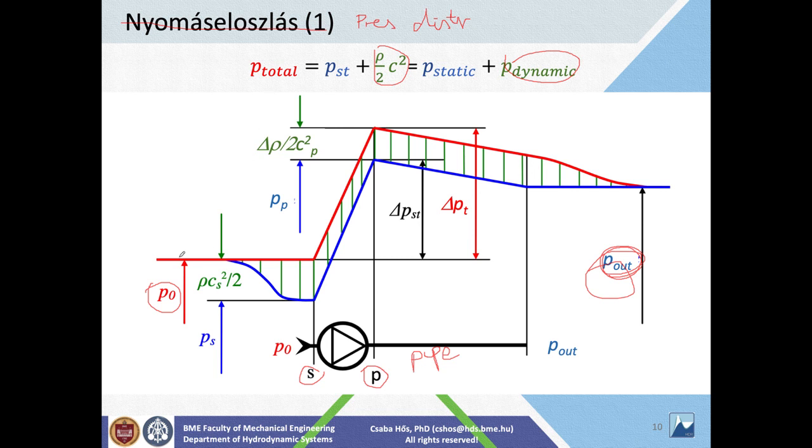Okay, so we are starting off somewhere far away from the fan, and as the gas approaches the fan, it accelerates up to the suction side. If it's accelerating but the total pressure is constant, then the static pressure will drop, and the difference in between will be the dynamic pressure. So you will measure a slight depression, a lower pressure, at the suction side of a fan.